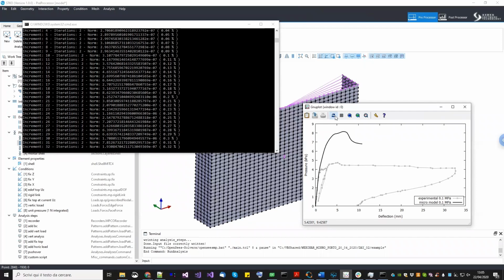And then in the post-processor, we are going to see how the total vertical reaction changes from the first step to the other when we change this dilatancy parameter. So basically, this is one parameter that you can calibrate using simple shear tests on mortar joints and measure the uplift.